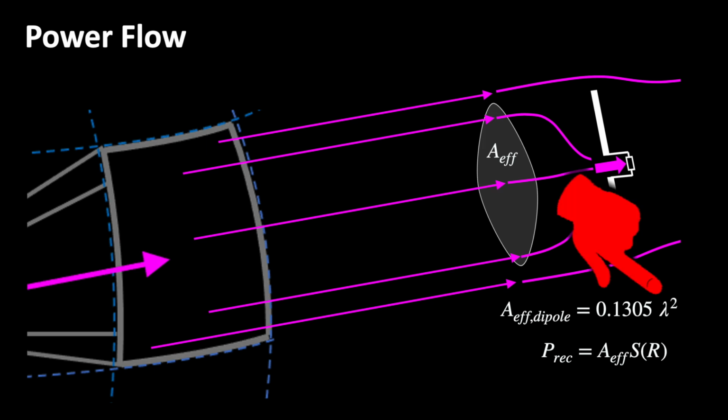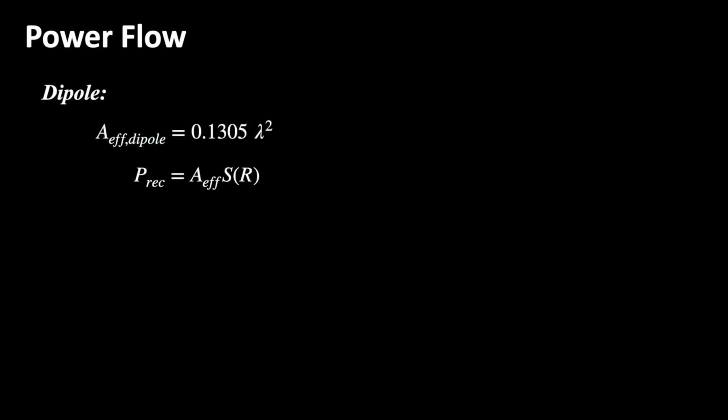Unfortunately, this equation depends on the frequency, because the dipole antenna must be adapted to the impedance of the receiver by means of a suitable length, for example half a wavelength. So the effective area of a half-wave dipole becomes smaller as the frequency increases, causing the antenna to absorb less power, even though its gain is always the same.